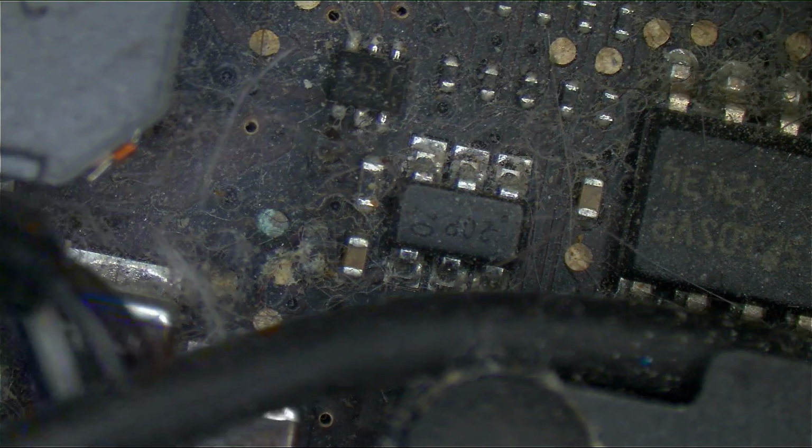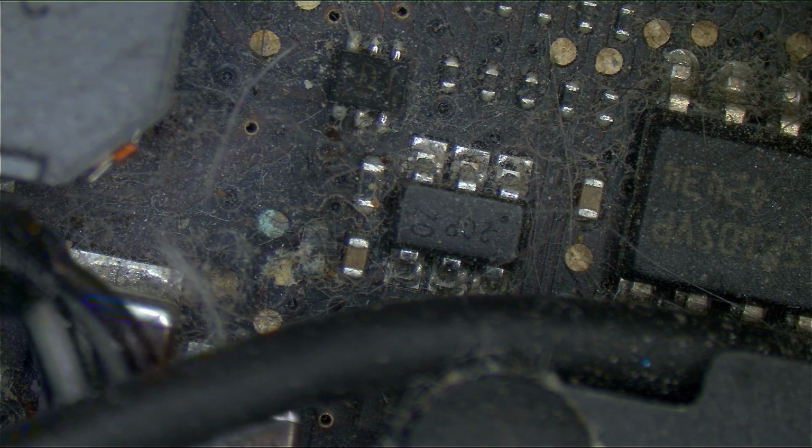So what we're going to do is we're going to measure the resistance of R9788. Now remember, we're not just measuring the resistance of this resistor, we're measuring this pathway. So you have a pathway from here to here, but we're also measuring the pathway between here and here, and here and here. So let's check R9788. We're going to measure R9788 over here, and we're going to see what it is that we get. So R9788 is going to be this one.